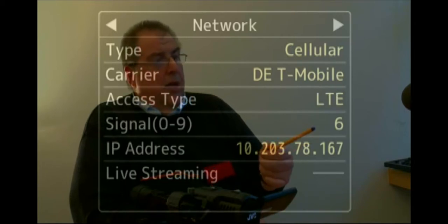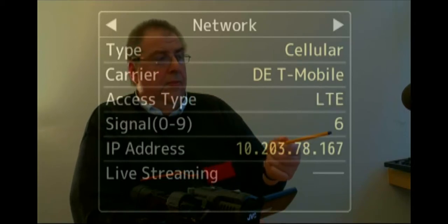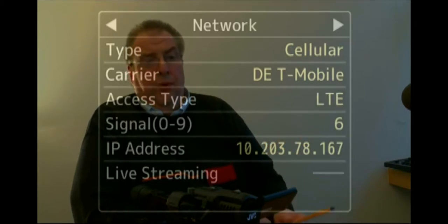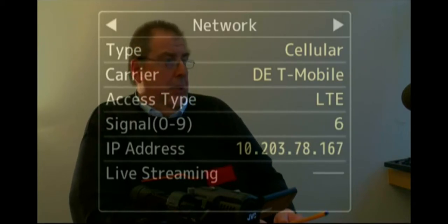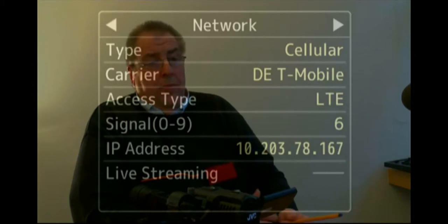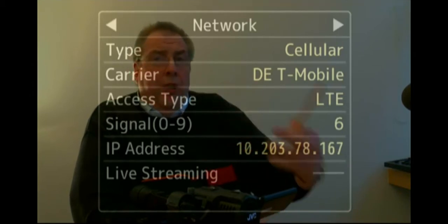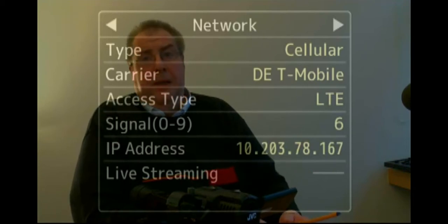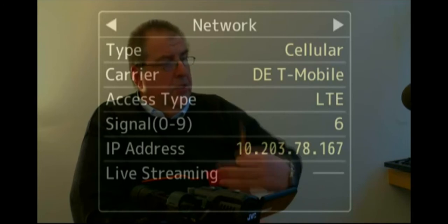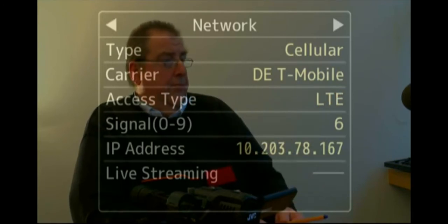If it's lower, the quality of service is not good enough to do streaming. And also keep in mind that the speed on 3G is limited, so it's good for an SD signal with 800 kilobit transmission rate. Anyhow, the GY-HM650 allows you many kinds of streaming rates from 250 kilobit up to 8 megabit, depending on which resolution, etc. you use. But this is a topic for the next seminar.